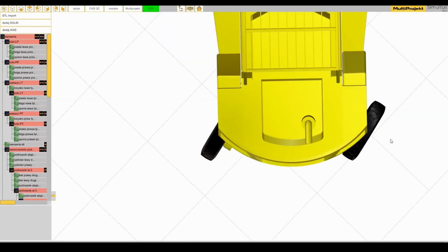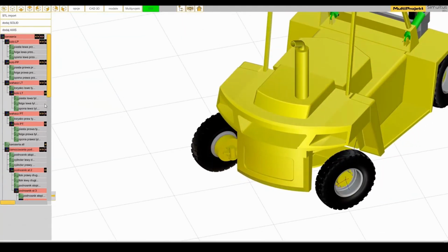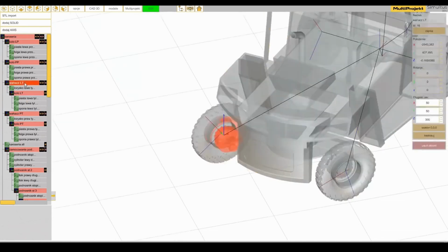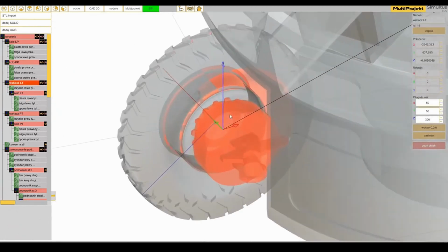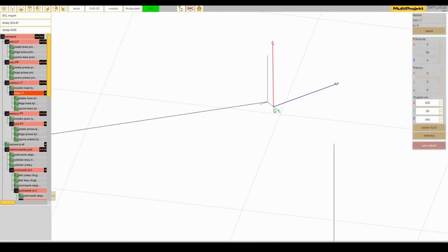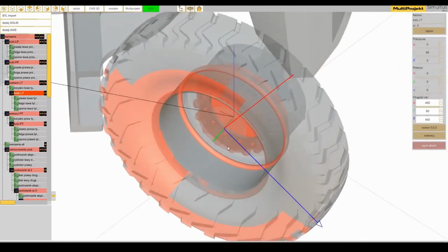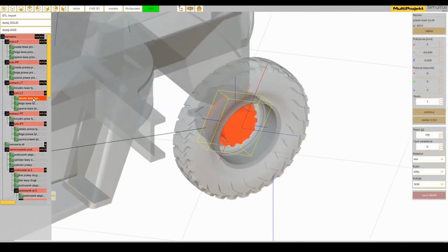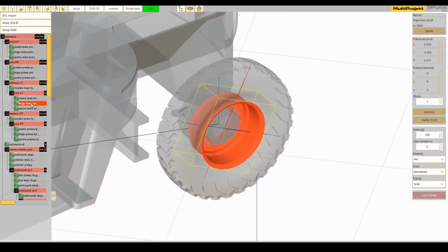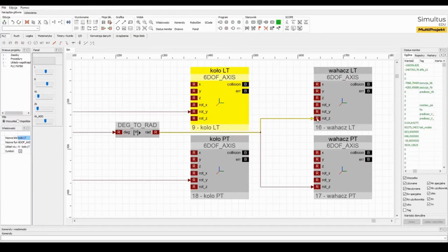The rear wheels are swiveling. That is why in our model we first defined swingarm systems, turning in the vertical axis. Only after that, we connected them to the coordinate systems of the wheels, which are rotating like the front wheels in the y-axis. The 3D solids of the wheel, rim and tire are connected to the latter. In the diagram, the swingarm system will be rotated in the z-axis and the rear wheel system in the y-axis.